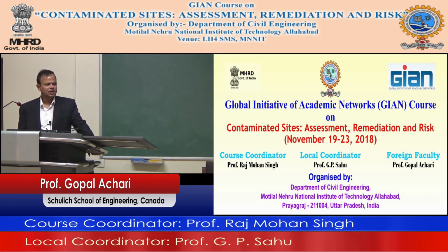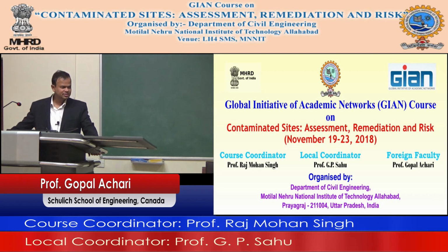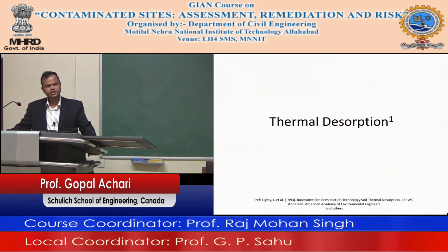Okay, so if you have a hazardous material, you don't know what it is, fairly hazardous material, you don't want to desorb, because once you desorb it, you still have to treat it, right? And you don't want to be dealing with the desorbed gases or something that is coming out, then incineration is the way to go. But it is an expensive way of treating soil, because you are burning everything.